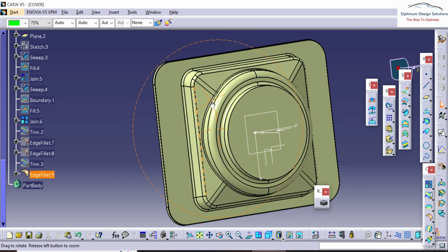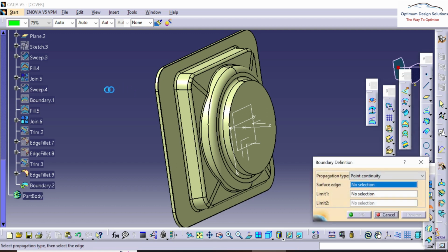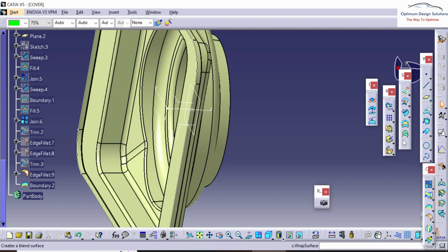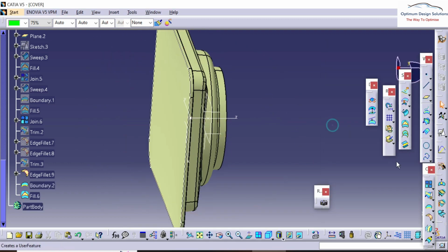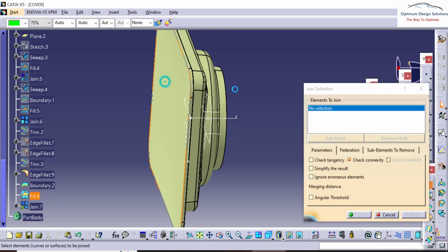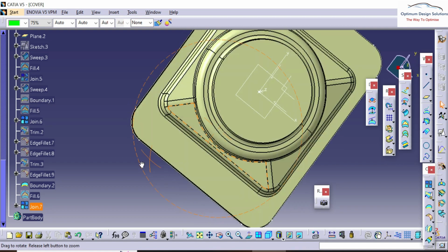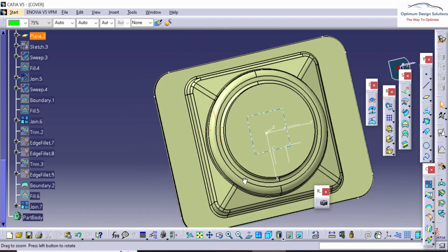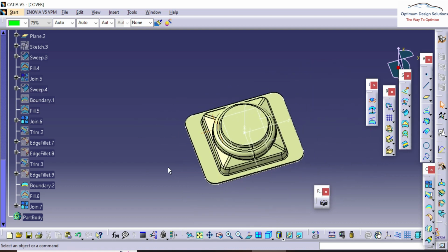So here the cover, which protects the other parts of the motor or whatever the assembly, gets created. Now we will move towards closing this total shape. Before that, as this is a plastic component, some depression should be there to provide strength. So at the four corners, or diagonal corners, we'll apply some projected depressions.